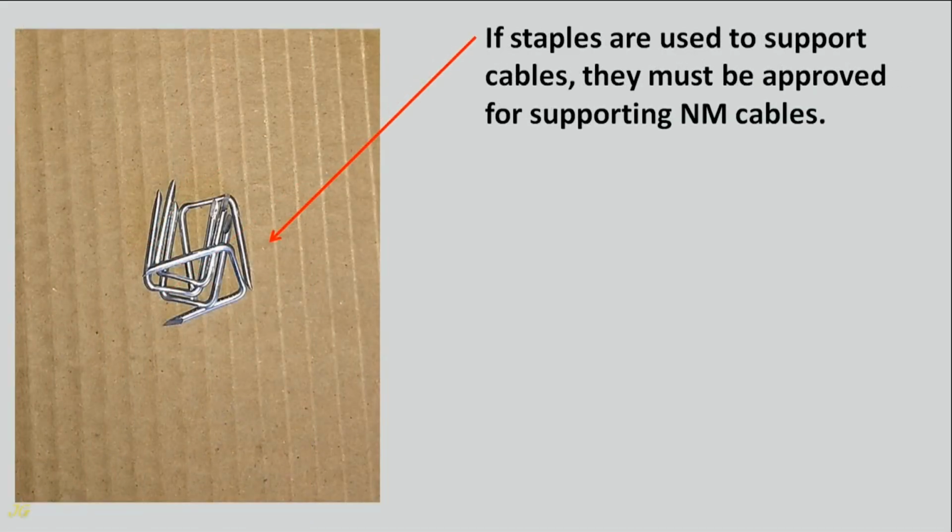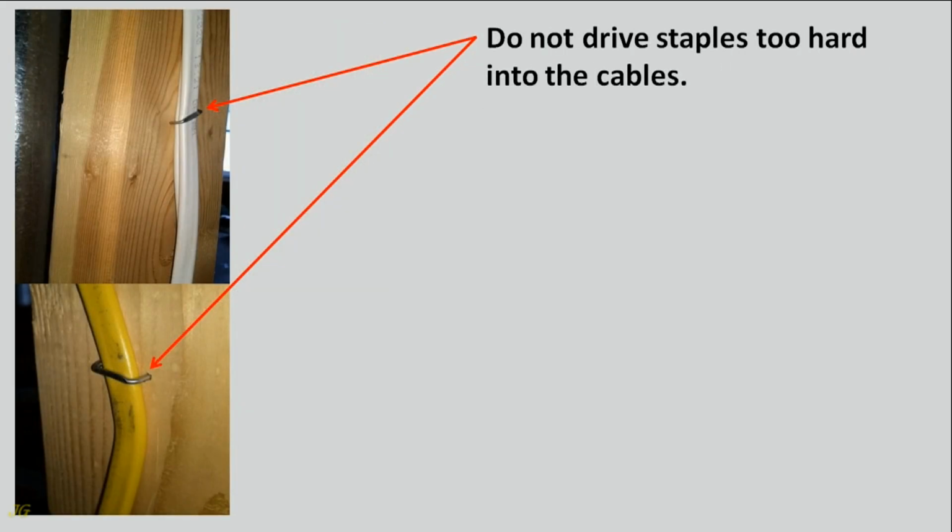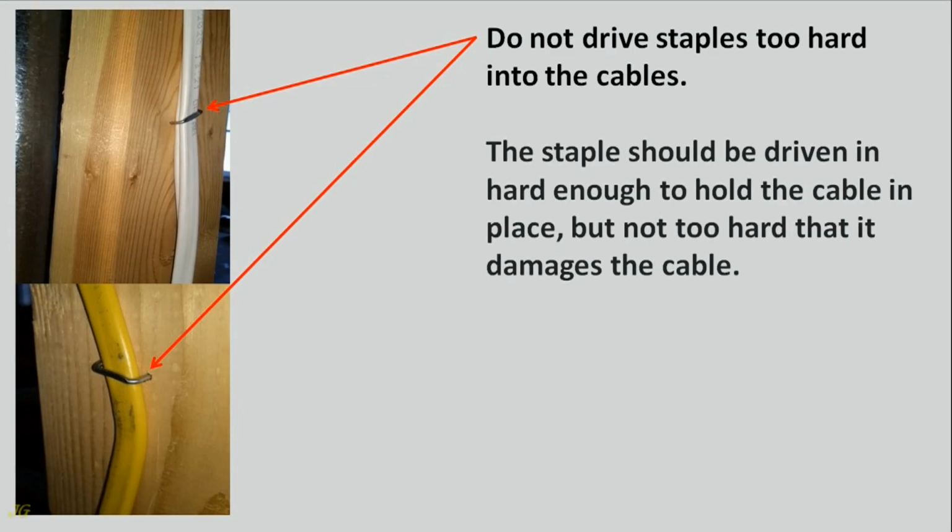If staples are used to support cables, they must be approved for supporting NM cables. Do not drive staples too hard into the cables. The staples should be driven in hard enough to hold the cable in place, but not so hard that it damages the cable.